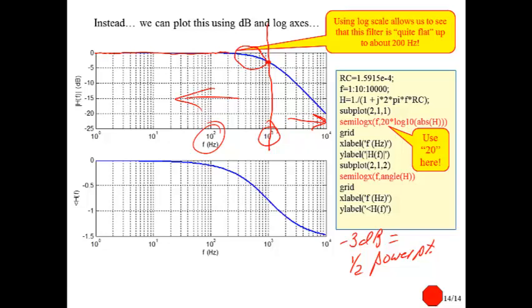So remember, an ideal low-pass filter would be perfectly 0 dB up to our cutoff, and then it would go to 0 in non-dB. What is that in dB? Minus infinity. All the way down off from the chart. So that's the idea there. And we'll be switching back and forth between dB plots, log axes, non-dB plots, linear axes, whenever is needed.